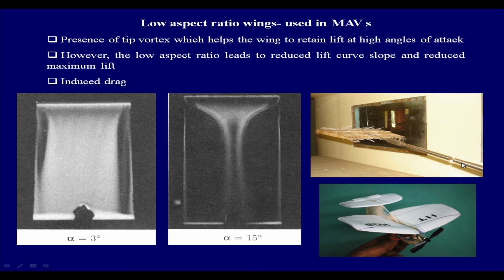Yeah, I mean, of course, you have to make sure that finally you are able to get the aerodynamic forces only extracted from there. How do we subtract? Yeah, the dead weight part, before you start the test, you have to do the setting so that you can actually eliminate the dead weight part. Yes, that is a little issue that is always there, certainly.